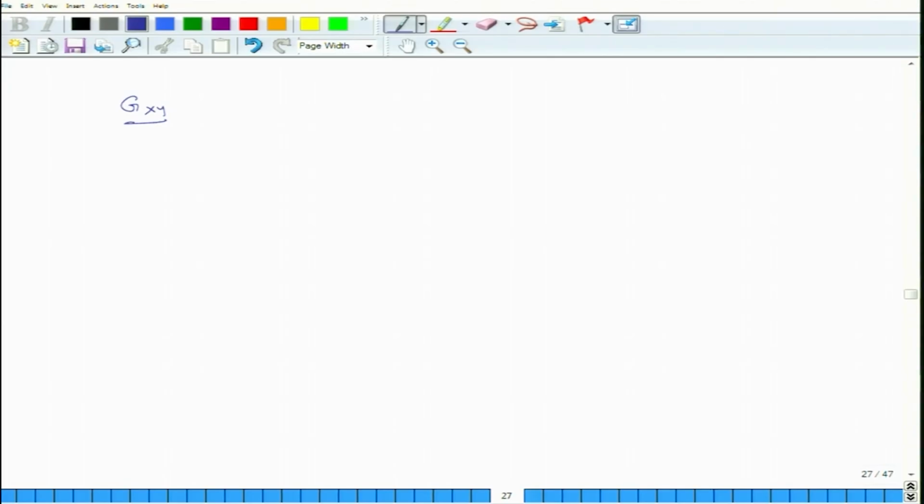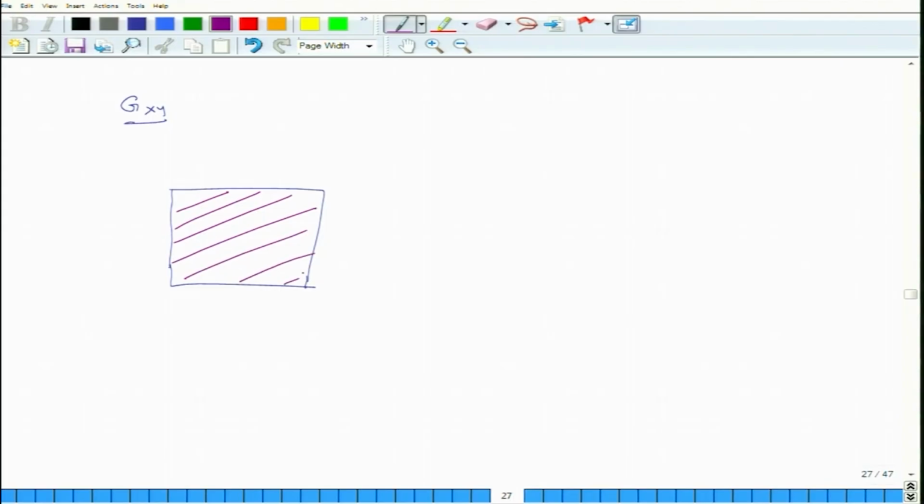So, what do we do? We again go back to our basic concept. We have an orthotropic composite lamina. The lamina is loaded in this direction, is not especially orthotropic, and so this is my x axis, this is my y axis, this is my L axis, and this is my t axis.